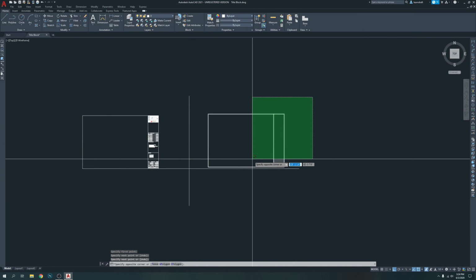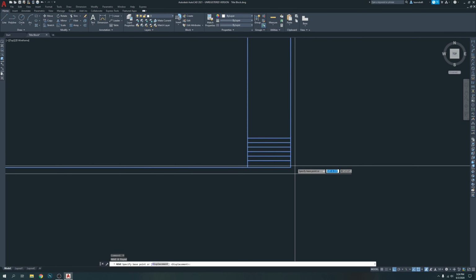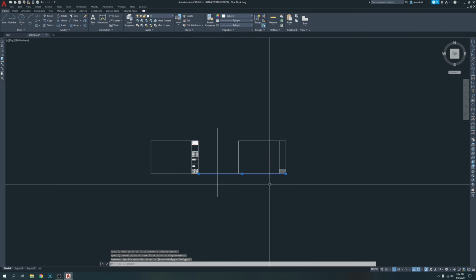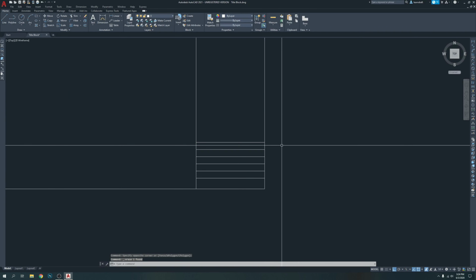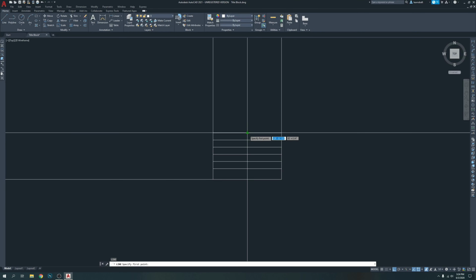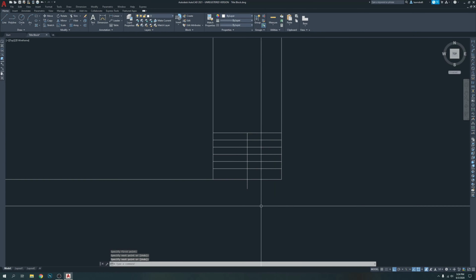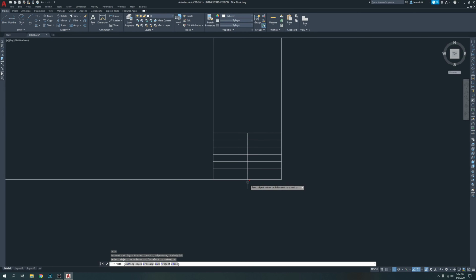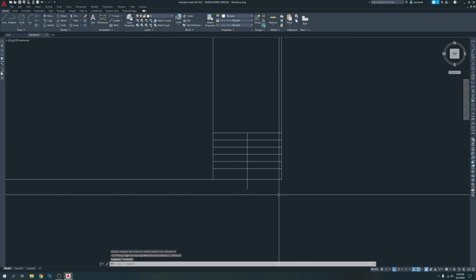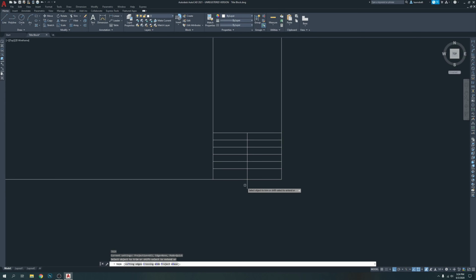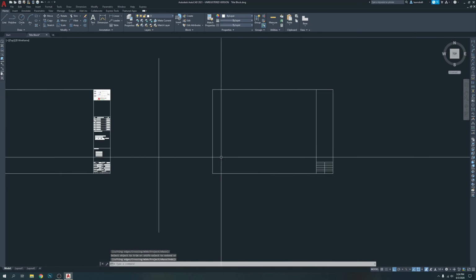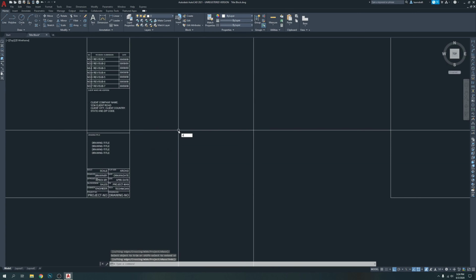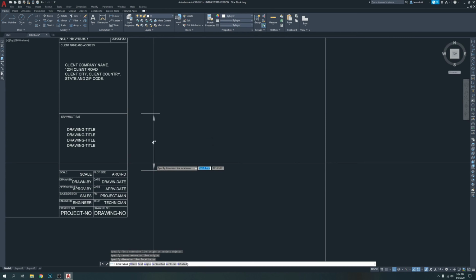I'm just trying to make it align. So let's click here, delete this. It's going to be a little helpful. So draw another line here. I drew a little extra, trim it. In 2021 you just press TR from the beginning, TR, enter. You just click on any line and it goes away. You do not need to press an extra enter like until 2020. Click enter. So this is done. Now we have this gap. I think I left it for 4 inches. Yes, 4.